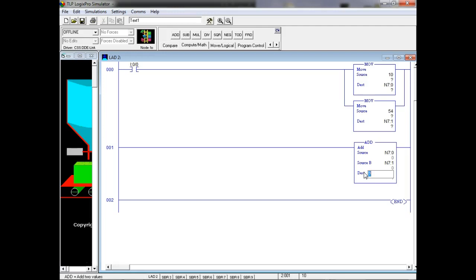So, preset of the counter. You could put it in a preset of the counter. You could put it in an accumulator of a counter. You could put it in the preset of a timer. You can't change the multiplier. You could put it in the accumulator of a timer. So if you wanted a timer for some reason, especially down counters, you could literally make it count down. You can make it count down, guys, but you have to preload that accumulator with a number. And then it would actually count backwards, but the problem is when you reset it, it would go to 0.